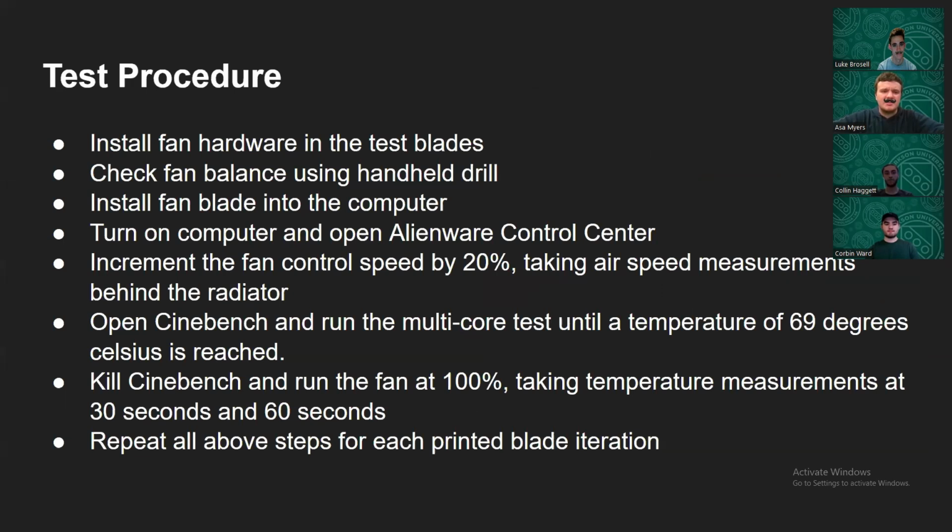Our test procedure started with the assumption that you have all of your fans ready and printed out. Once you have your fans, you would install the fan hardware into the test blades and then check the fan balance using a handheld drill. This was just to ensure that no damage would immediately be done if you turned on the PC with the fan running. Once the fan was checked for balance, the fan blade was installed in the computer, and the computer was turned on, and the Alienware control center was opened up.